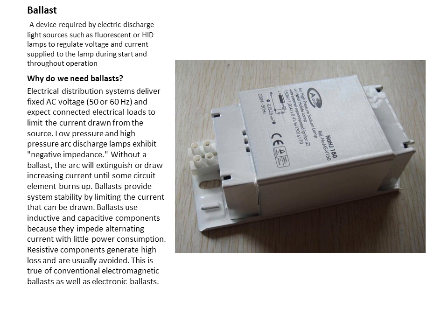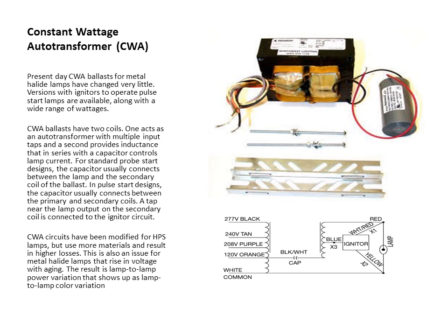Ballast provides system stability by limiting the current that can be drawn. Ballast uses inductive and capacitive components because they impede alternating current with little power consumption. Resistive components generate high loss and are usually avoided. This is true of conventional electromagnetic ballast as well as electronic ballast.